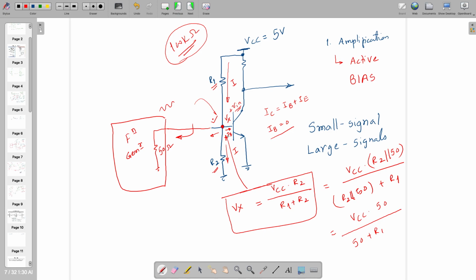So what is the suggestion? How do we modify this circuit to make sure that you are going to see Vx equal to VCC times R2 by R1 plus R2? Now you can say, Piyush. Yeah, so use a big capacitor here. This will block the DC current which is coming from here. But when you are applying AC analysis, this AC will go that side. So it will allow only AC from the input side and will block DC from the top side. Right? This is how it works generally.